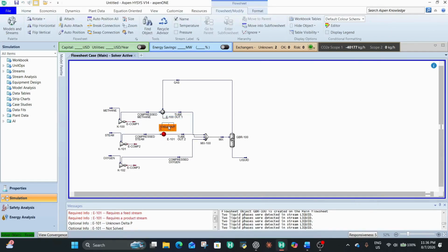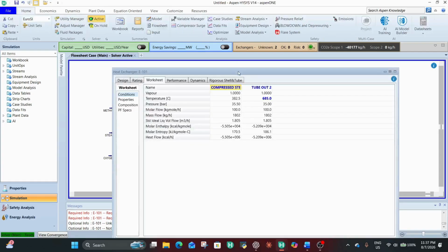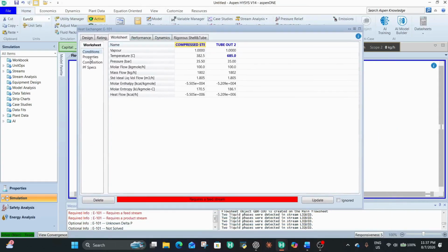So let's see what the new temperature looks like. 686.9, from 900 we dropped in terms of temperature, and the reason for that is basically the change in temperature difference, and we have more flow rate over here plus our latent heat energy. All that works to our advantage, but we will most likely have a temperature cross here.